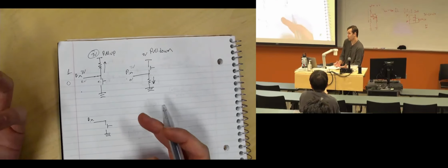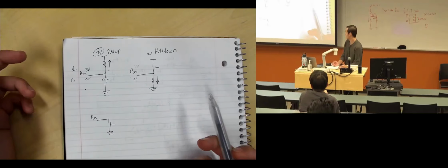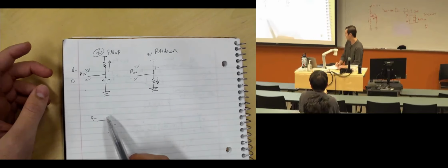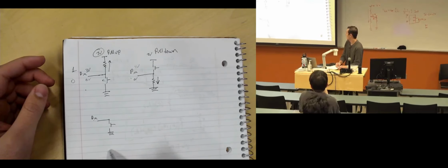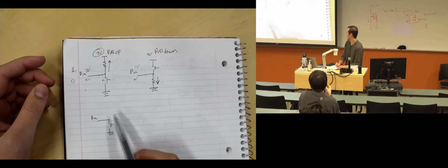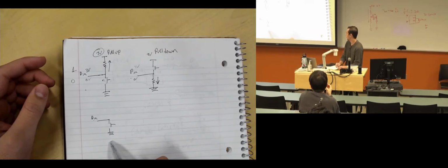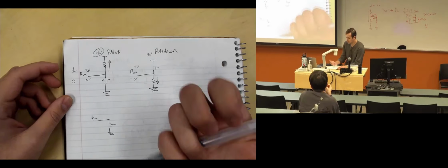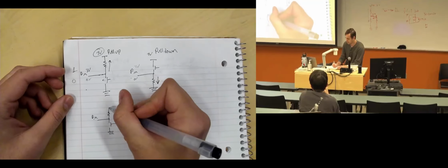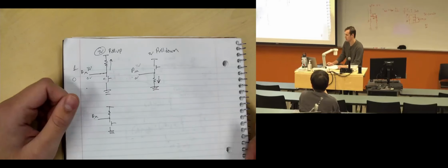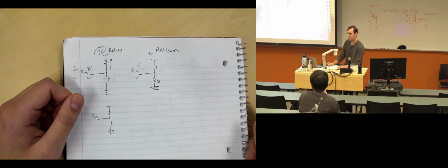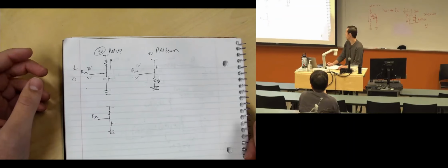Great, we don't know. We don't know what the voltage is, right? It could be anything, it's floating. It's not connected to any nodes or any voltage sources, whether that's ground or 3 volts. So we need a resistor to pull that up. That's where the name comes from, right? Does that make sense? Because this is normally a tricky thing.